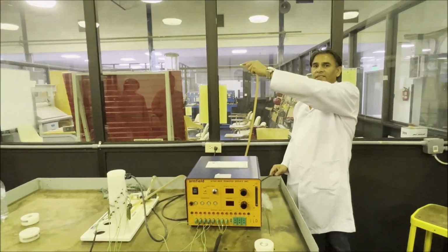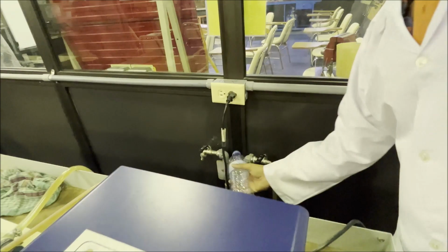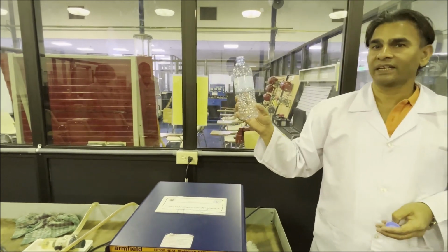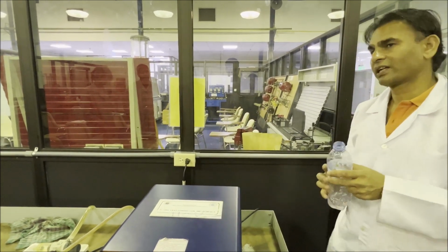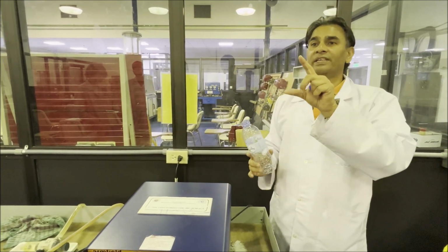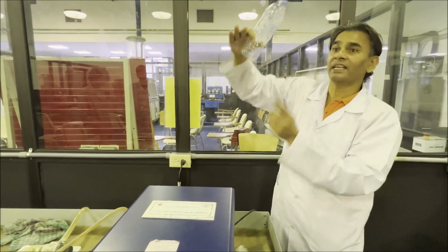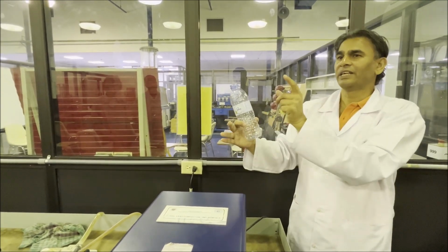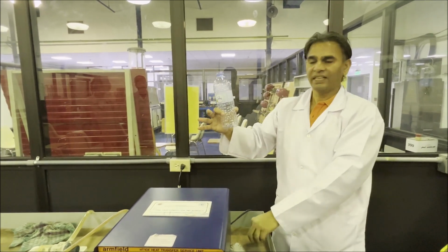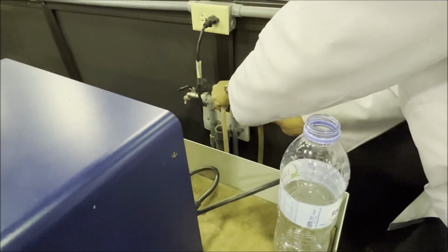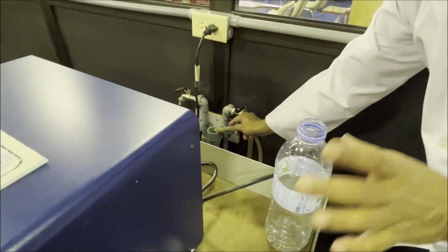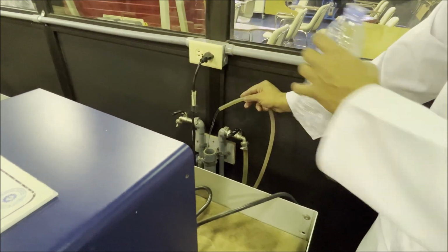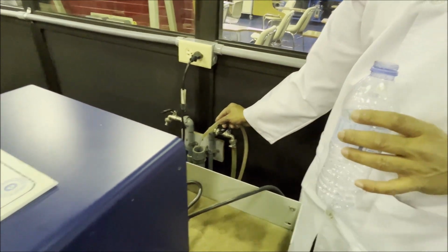Okay, second step. This is a water outlet. Start the water outlet. This water bottle, how much is written? 600 milliliter. Okay, less than 1 liter. So I need to maintain the water flow rate at 1.5 liter per minute, like a 1.5 liter Coca-Cola bottle in a minute. So this is half, 30 seconds. In 25 to 30 seconds, this will be filled. I need to adjust the water flow rate. It's not important, but approximately, if you check, this is 1.5 liter per minute. You have a stopwatch. Can you start the stopwatch? 1, 2, 3, start.